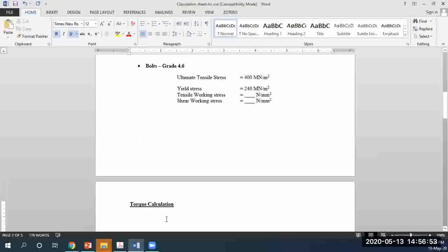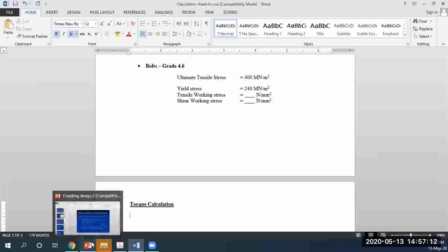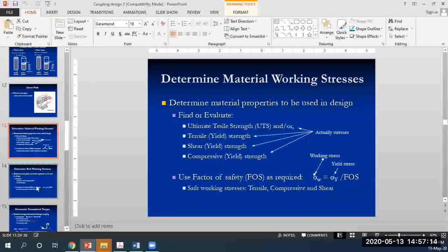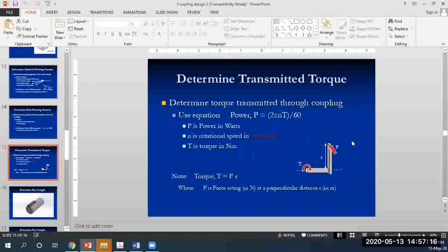Okay. So now we talked about that there is 75 kilowatts of power being outputted by the drive shaft, and the shaft will rotate at 25 revolutions per second. The shaft has a diameter of 48 mm. Using all that information, and these notes here, determine how much torque is generated.